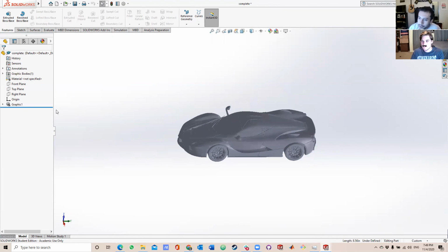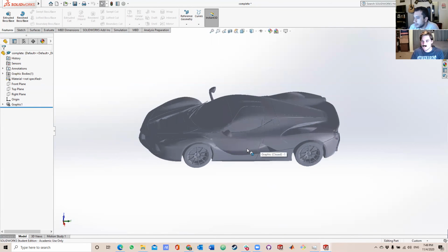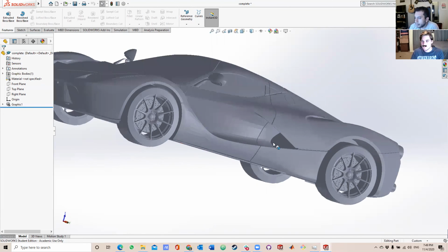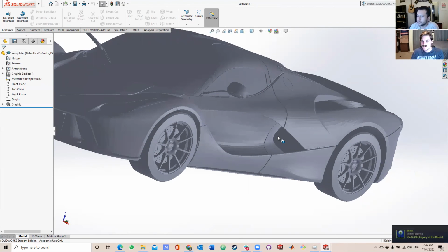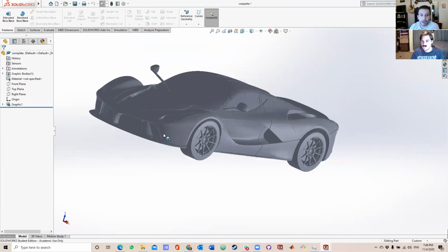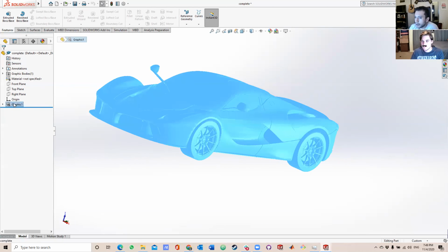And so there are multiple ways. So this one came in as a graphic, which I've never actually seen before. But usually what that means is that they have some real complex shapes, and that SolidWorks, when it looked at it, said, honestly, I have no clue how they made that. I'm not even going to try. But if you have something simple, like a square, SolidWorks will make guesses. SolidWorks will say, I think that this was an extrusion across the whole thing. If they made another extrusion, another cut, it gives you kind of a guesstimation as to how they made that.